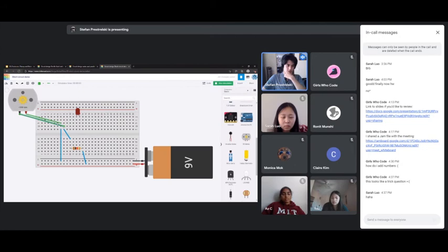With a motor is one of the things you can flip power and ground. What's going to happen is it's going to turn in the opposite direction. And this is how an electric car achieves reverse. It just simply flips the direction the current is going, essentially. Now, most electric cars use alternating current, not direct current like this. But for a smaller vehicle, this is how you can achieve directional control.